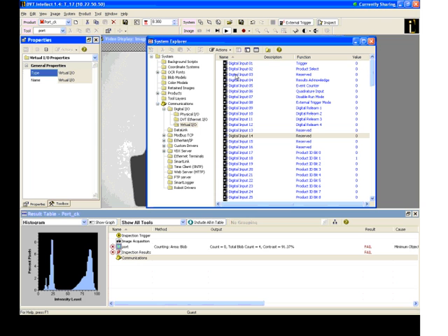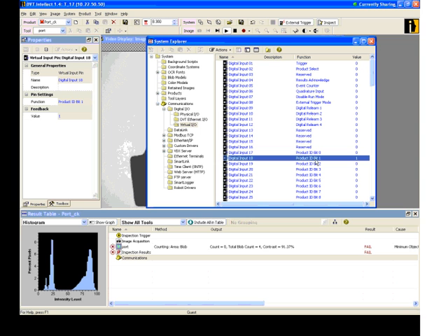Now these are going to show you representatives of all the configurable pins, all the configurations you can have for these. Notice we have here trigger, reserve, event, digitals, reserve, product ID bits right here. You'll notice this product ID bit is 1. That's because in that breakout board configuration, I forced that bit high.